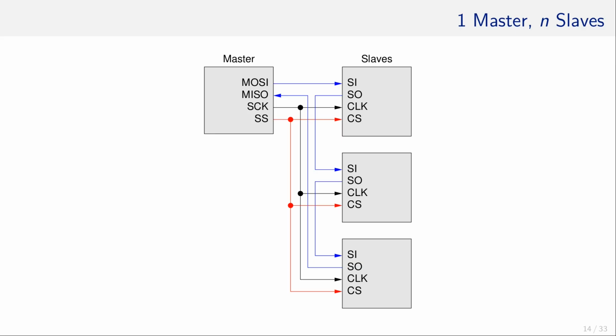After those 8 cycles, the dummy byte is in the first slave and the data resides in the second slave and is read here. Since all slaves are in a chain, this topology is also called a daisy chain. It reduces the amount of wires required, but needs more dummy bytes to be sent around.